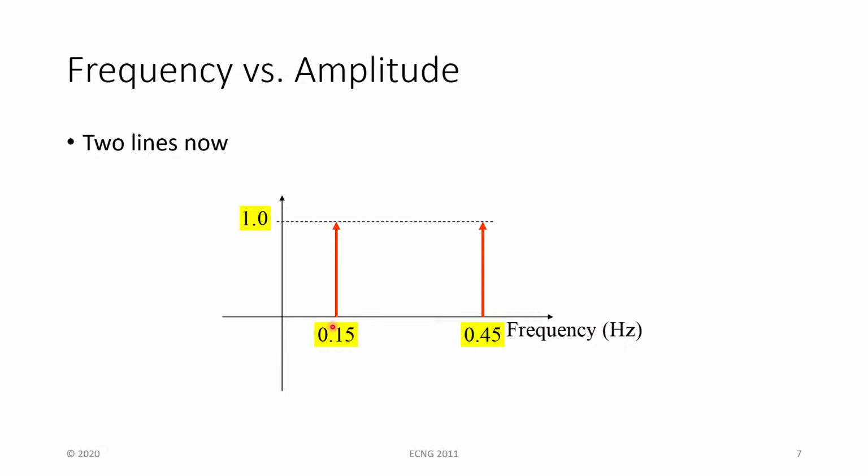So we just draw each one of these signals individually in that particular plot. We draw our cosine omega t representation here, and then because of the addition, we also draw our cosine 3 omega t representation. This representation only exists for when you add sinusoid signals together. It's basically the addition of each one of those frequency components, and you just draw each one respectively, independent of each other, on the graph.